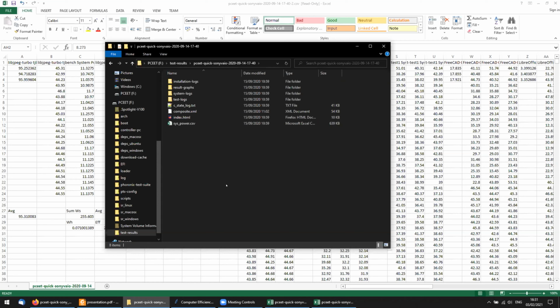And this is why it's important to synchronize the clocks on both computers, because the merging is based on the timestamp. So here we have power measurement with timestamp. On the other side, on the unit under test, we have measured performance also with timestamps. And the results are merged internally in the unit under test.